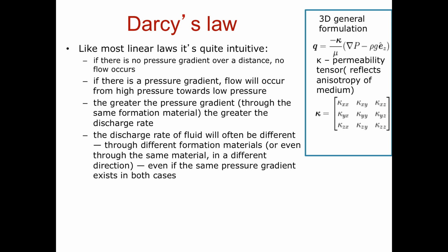Now, as you actually go into larger discharge rates and larger pressure gradients, you might actually have onset of turbulence in some of the flows. So there's a built-in assumption in Darcy's law that you actually have laminar flow. So if you don't have laminar flow, then you actually have to either know that you're working with an oversimplification that might not be as accurate, or actually use corrections to Darcy's law that are present for different flow rates. And we're actually going to mention some of those corrections together with those friction factors in the chapter that is coming up after this topic.